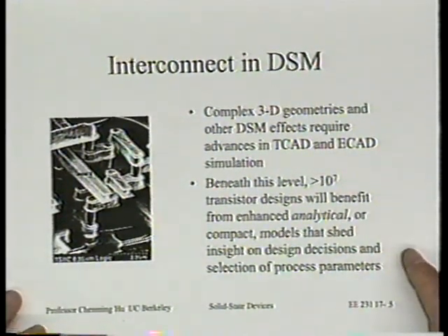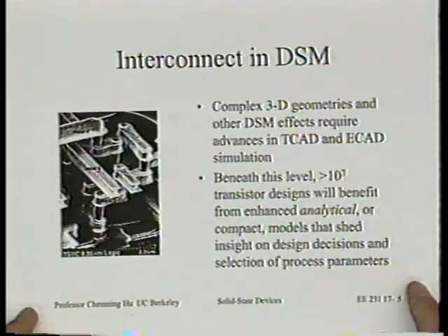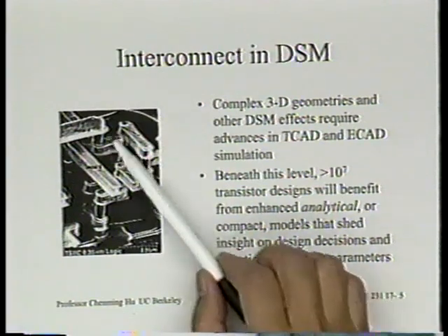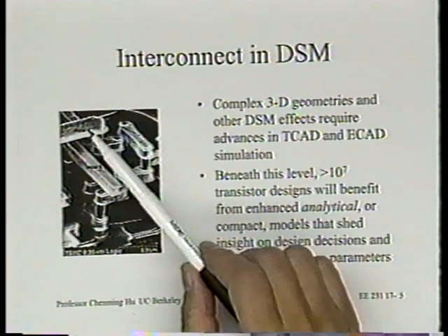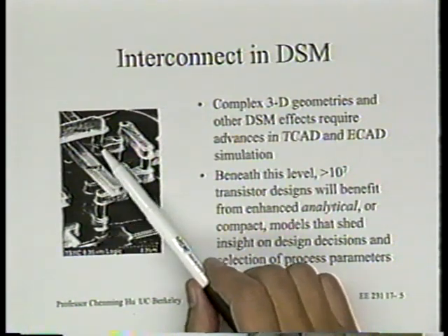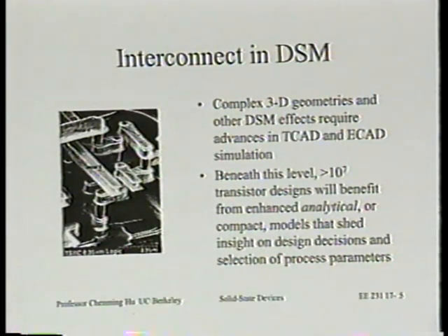All right, here's an interesting picture that comes from TSMC. This is a logic process, has 4 layers of metal, and after the chip is done, you just dip the chip into acid so that SiO2, the intermetal dielectric, is all etched away. So what you see is the skeleton of this metal around. So you see the top one says metal 4, next is metal 3, and you notice between metal 3 and metal 4 there's a via here. It looks like a cylindrical post.